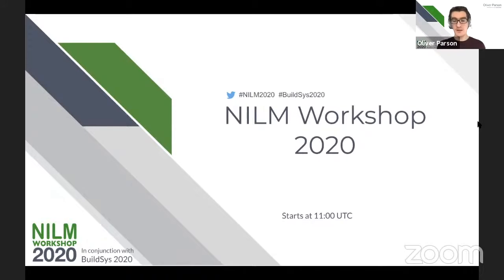So throughout this workshop today, you're probably going to hear this problem discussed through a range of data rates, ranging from high frequency data collected at either thousands or maybe millions of times per second using bespoke hardware. You'll probably also hear other data rates from, say, 1 to 10 second data that you might be able to extract from a smart meter over a home area network or a local network. But you also might hear discussions around 15-minute or 30-minute data. This data is typically available from smart meters, but over a wide area network as well, also referred to as AMI data. And really, I think NILM is sort of the same problem, but it changes depending on different data rates and different hardware that's used. That's what we'll be discussing today.